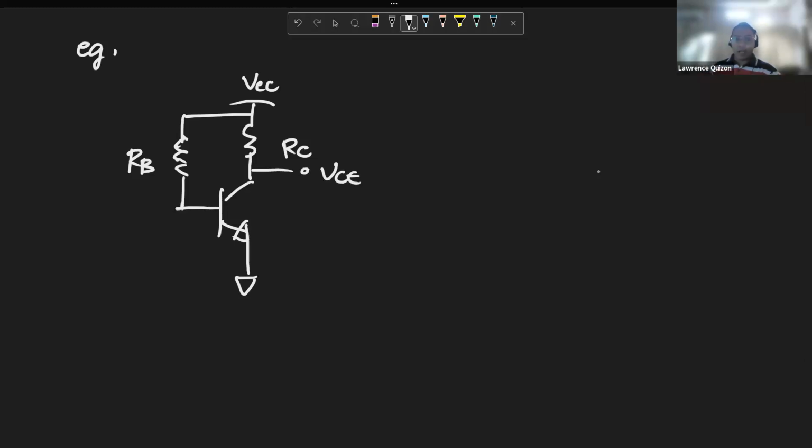So now, we're going to have a DC bias, no? Dito sa circuit na to, right? So let's calculate. So our calculation will go like this, diba? So we're going to assume na naka-on yung transistor as we usually do, right? The first assumption is forward active. Then we check if it's in saturation. If it is, then okay, we reanalyze assuming that it's in saturation, no? Yun yung flow natin.